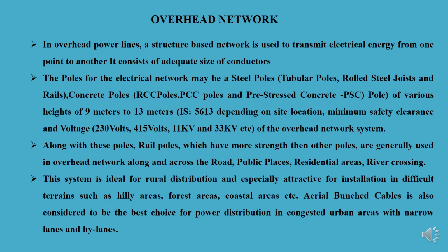That pole may be a steel pole, right? In steel poles, there are tubular poles, rolled steel joists and rails. It may be a concrete pole, which may be RCC or PCC poles, and pre-stressed concrete poles also, of various heights from 9 meters to 13 meters. That depends upon the site locations, minimum safety clearance and voltage, right? So there are conditions.